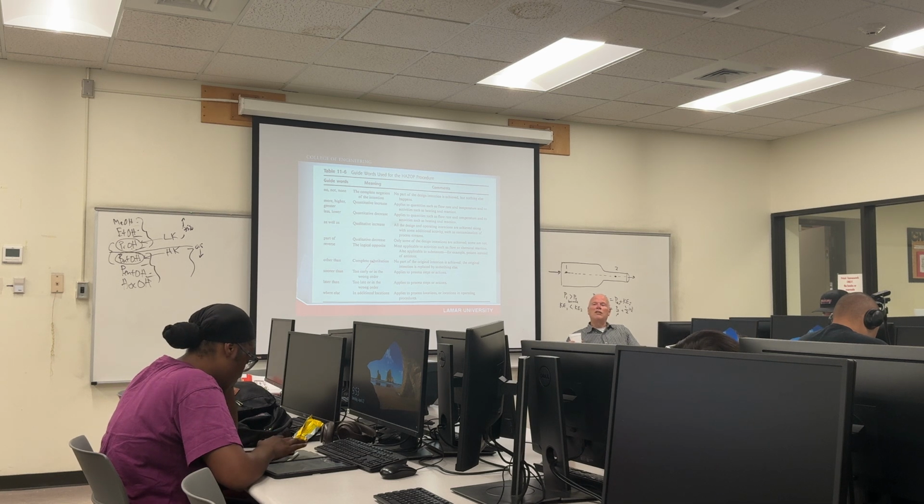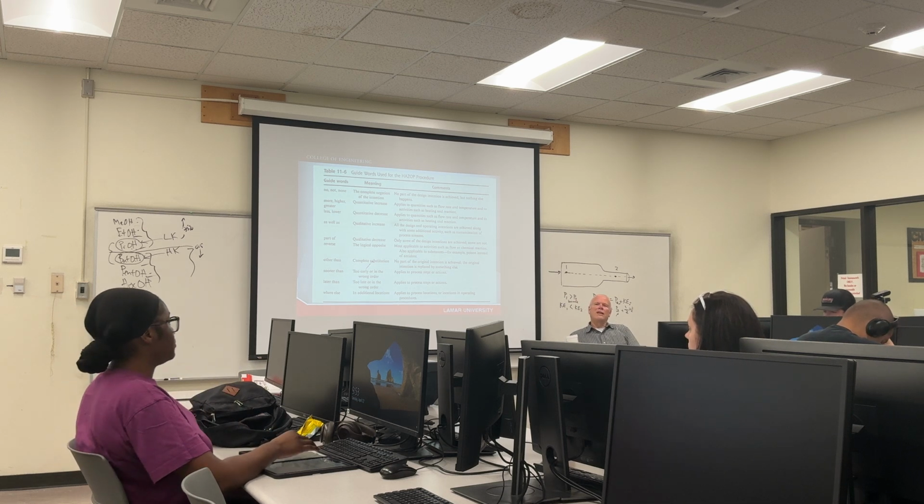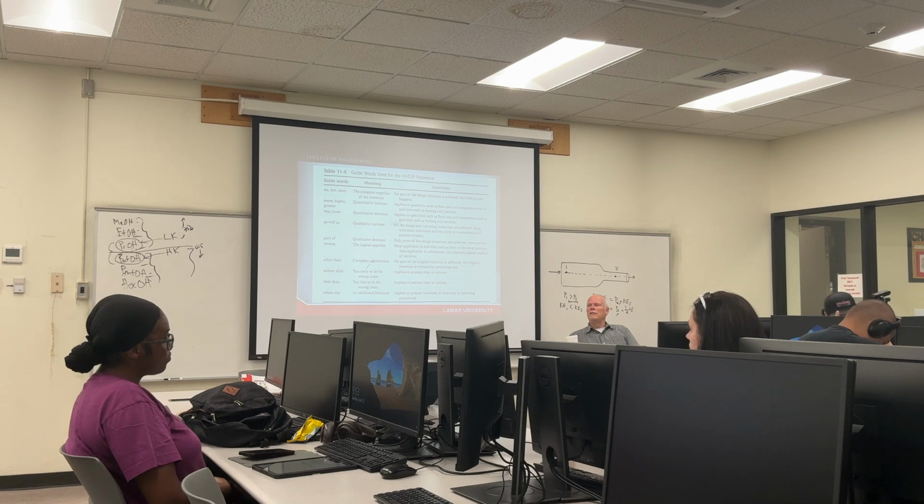So what happens to a column if your reboiler stops working? Cools down, stops separating, everything goes down to the bottoms. Yeah, it just stops separating, gets cold. Does it cause any trouble that you would worry about in terms of hazards? What kind of hazards does it give you?